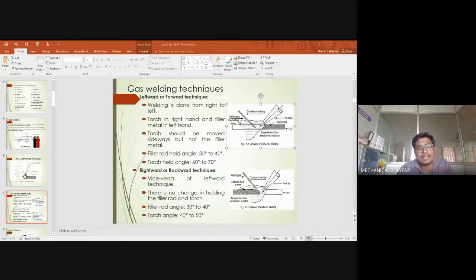We have metal inert gas welding, which we will call MIG welding. It is otherwise called gas metal arc welding, or GMAW welding. The electrical arc is produced between the workpiece and the electrode. It is the same as the previous process. The electrical arc has to be produced between your electrode and the workpiece. The electrode holds a consumable metal wire electrode which is continuously fed from a reel feed unit. So here you can see the absence of a reel feed mechanism in the TIG diagram.